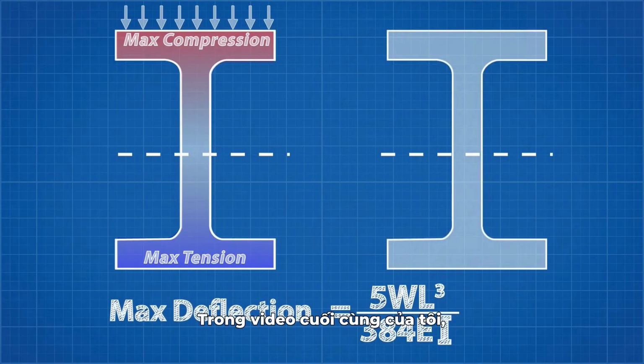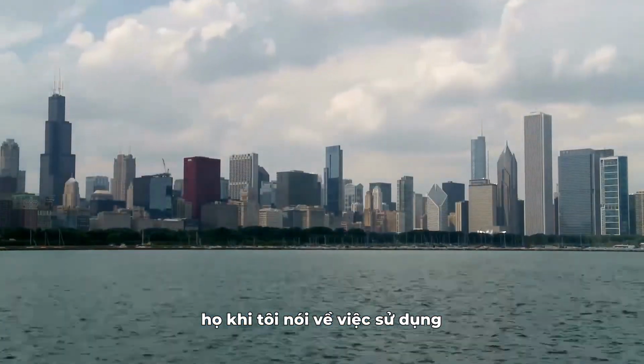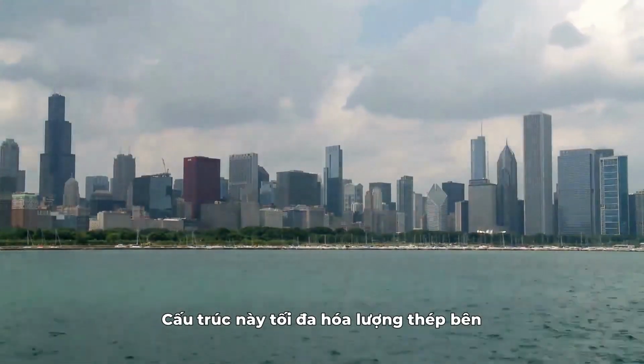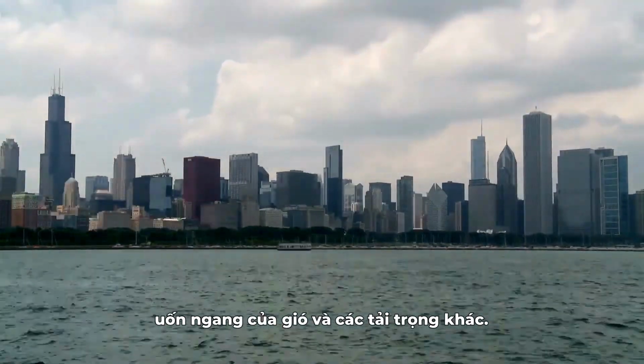You can see this idea put into action all around you. In my last video, I mentioned just one of them when I spoke about the Willis Tower using a bundled tube structure. This structure maximizes the amount of steel on the outside of the building to maximize its resistance to lateral bending from wind and other loads.